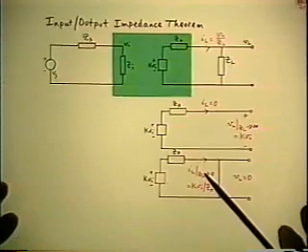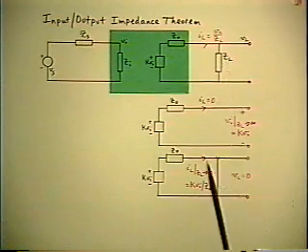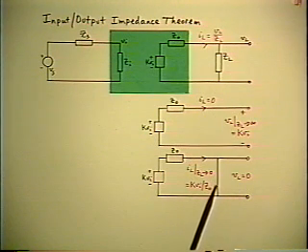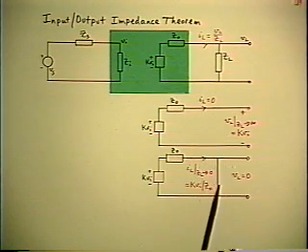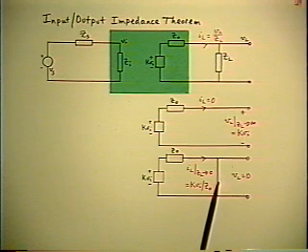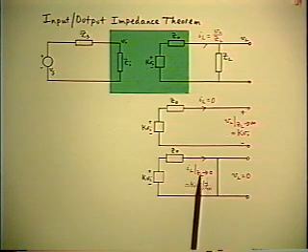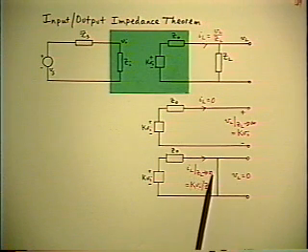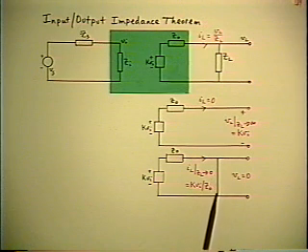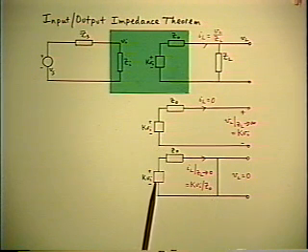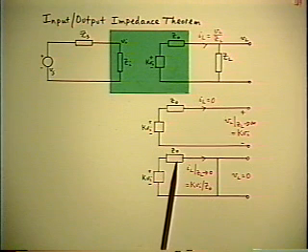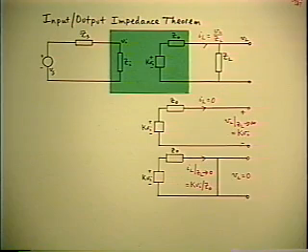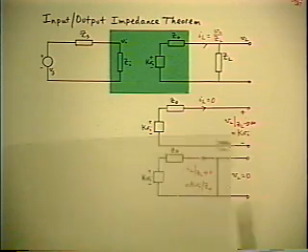Go back to the general case and make the opposite extreme condition. Short circuit the output and ask what is the current that flows through the short circuit. And the notation is IL under the condition of ZL going to 0 simply means the short circuit current. And what is it? Well, it's equal to the value of this Thevenin generator divided by ZO, the output impedance, obviously. Then what you do is you divide the first result by the second one.